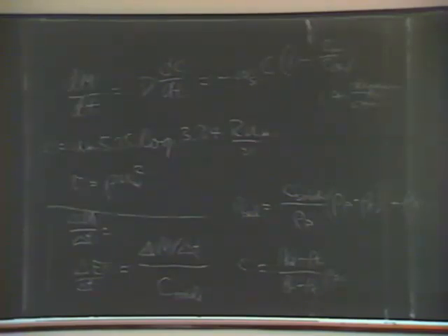So if you look at the region, and you can look at the weather system, you get some pretty good idea. If it's dry and cold, there may not be clays, it may just be silt. In Alaska, you find practically no clay at all, at least in the upper part of Alaska. But you find rock flour, which is 10 micron or smaller ground up rock, ground up by glaciers. And it's weakly cohesive, but it's not clay minerals.